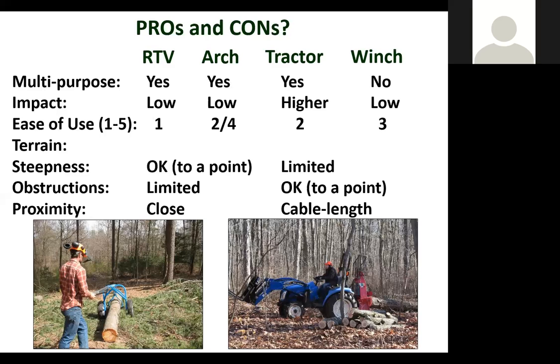Terrain is something to give some thought to. Steepness of terrain is a factor, for the tractor more of a problem than for the RTV. To a reasonable slope, the RTV will negotiate a slope fairly well. And I just would remind you once again, if you're going downhill with a load, drag the load.